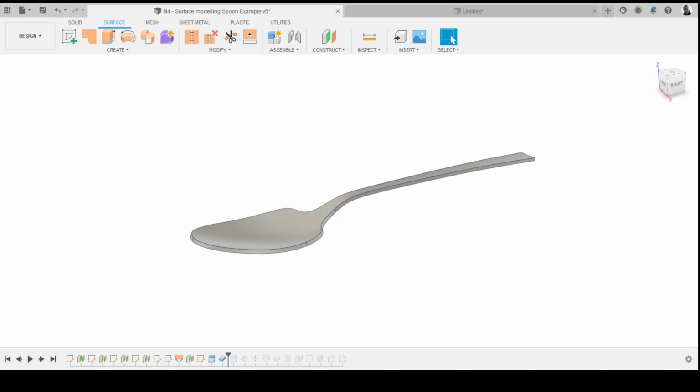And once you've got to that solid body, you can come out of the surface menu, go back into the solid body menu, and start doing other things that you might want to do to it. You might want to put fillets into it, you might want to drop text onto it, whatever you want. You can just treat it as a normal solid body because that's what it is. So the Thicken tool is really useful if you're just working with pressed stuff or things with even surface.